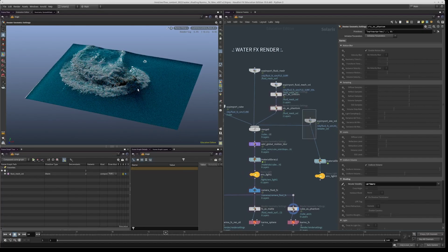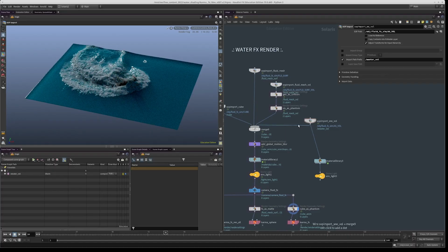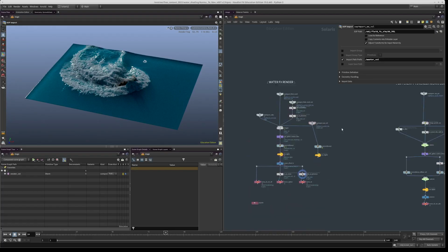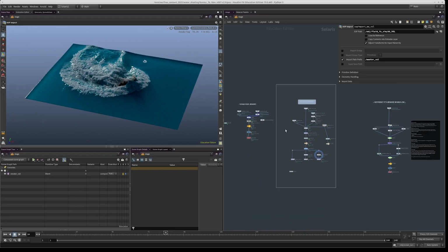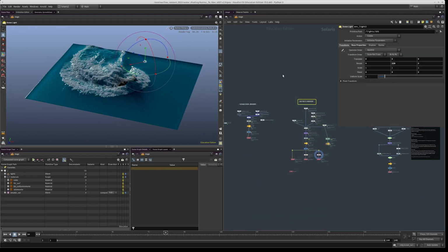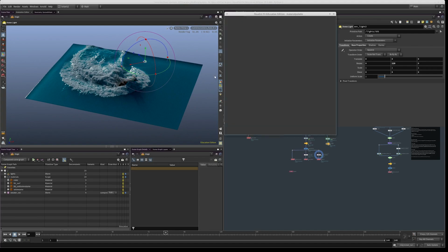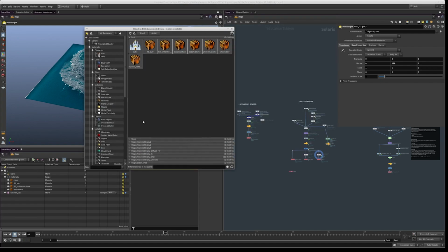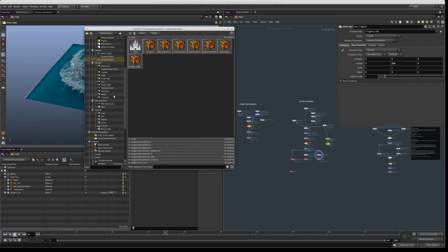And then if you want to render white water as volume, and with specular, that's how you do it. You compute the gradient on the SDF or on the volume. You cache that, and that's what gets used in the shader. And again, I think with the scene being provided, I will cache out one frame of each, so you can replicate this. You can use a shelf tool to create the basic shaders, but they're all pretty much the same. If you hit Alt G in Houdini, you've got basic liquid, ocean surface, and ocean volume. That's what the shelf tool is utilizing pretty much.